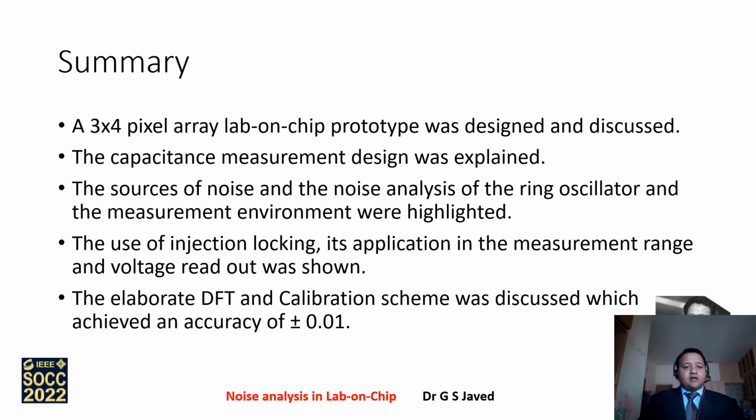So in summary, a 3x4 pixel array lab on a chip prototype was designed and discussed. The capacitance measurement design was also explained. We went through the sources of noise and the noise analysis in the ring oscillator, where the measurement environment and the system were both highlighted. The use of injection locking and its application in the measurement range and the voltage readout was shown, and an elaborate DFT and calibration scheme was discussed, which helped in achieving an accuracy or output linearity error of plus minus 0.1%.